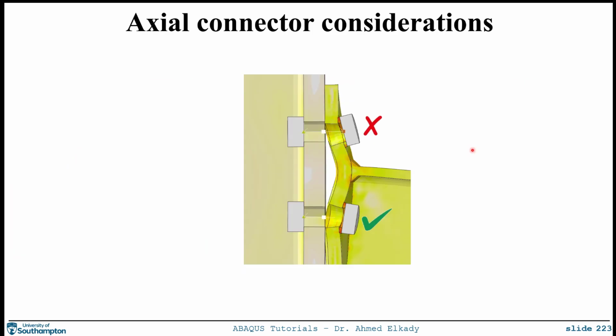In this case, the bolt over here, the bottom bolt, is fine because this bolt is subjected to tension. And you can see here that the two opposing reference points, or the bolt holes, are aligned during the loading. But in the top one, we have an issue. The issue is that the connected plate is bending or deforming in a way that pulls the plate downwards in shear, while the bolt head is rotating, but not moving sideways or elongating the bolt. So it's just rotating. This is comparable to what we call mode 1 deformation that is described in Eurocode 3.